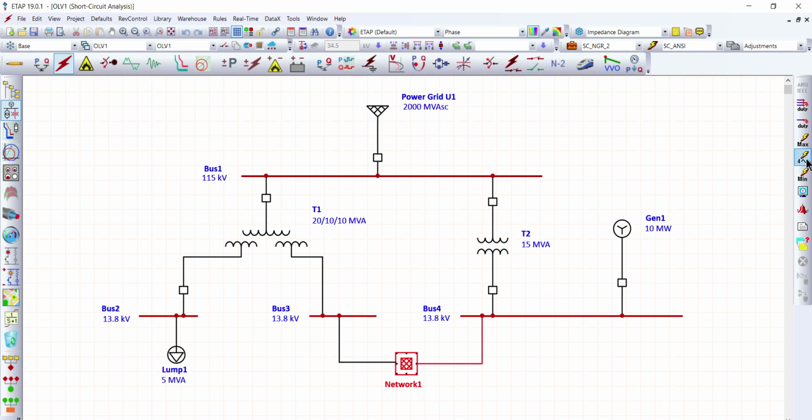Generator, motor, transformer grounding types, and winding connections are also taken into consideration when constructing system positive, negative, and zero sequence networks. Any adjustment for the impedance is taken as negative in order to produce smaller impedance and thus yield higher short circuit currents. Okay.